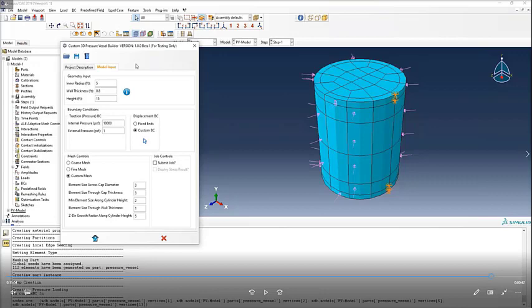Eventually you want to read the data from an input and then pass it on to the parameters that work with Abaqus internally. That can be a good start. So you look at how the structure is, start with a small problem, and then create complexity in it. Also, in Python scripting itself, there is a get input kind of functionality available, which creates a very simplified GUI. I think we had one slide that said that. Those very simple ones are ready pieces of code, so you can just call the function and it will create it.